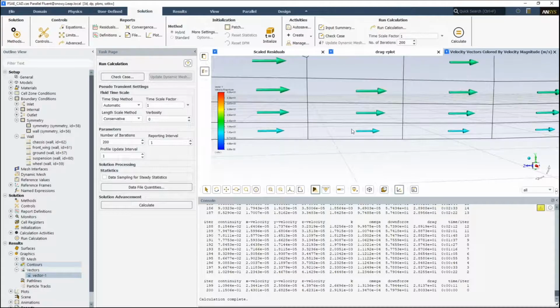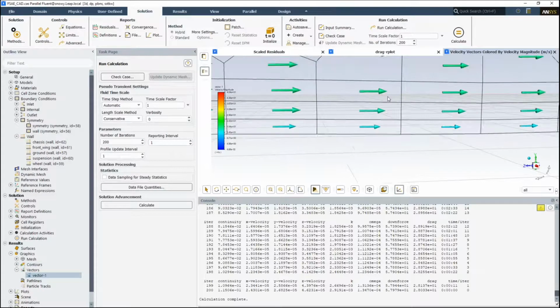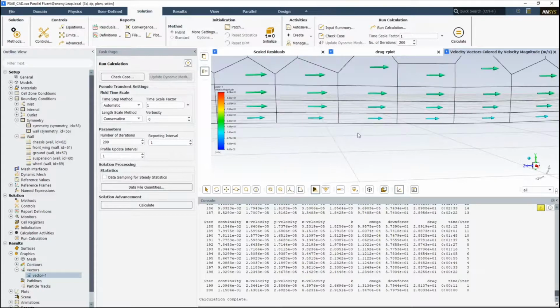I think it's important here to say that the reason that it's really important to pick up the boundary layer may seem arbitrary. It's not, and the reason is because of how much is happening in the boundary layer. So basically, what we have is this viscous sublayer that's all laminar flow, and then it turns transient in that buffer layer, and then goes into the log law layer. Where that boundary layer actually turns transient has a huge effect on aerodynamic properties.